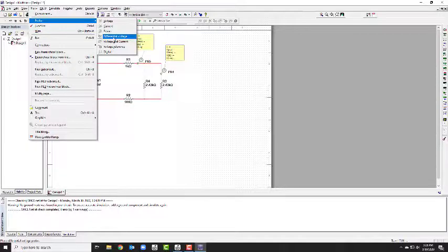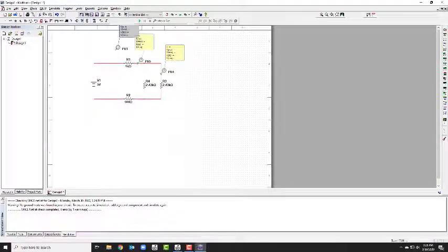So go back up here and place probe, and now, differential voltage. That tells me I want the voltage across a couple different points. Let's place a probe on this side of the resistor, and then another one on that side of the resistor, and let's see what happens. That was the differential probe. Let's go ahead and run that. 1.61 volts, that looks good.